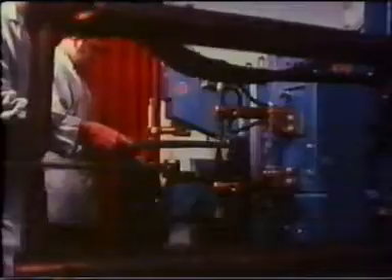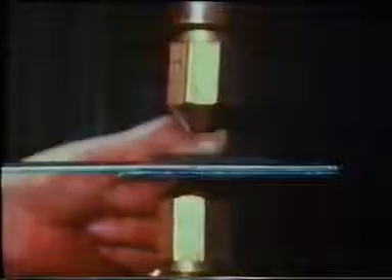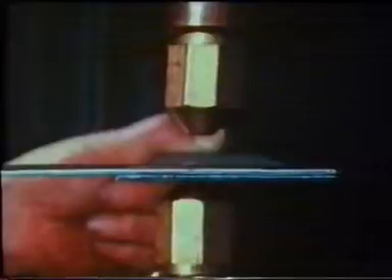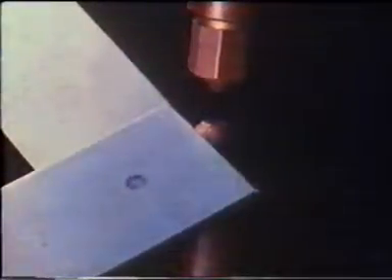The most common use of resistance welding is for spot welds. The spot welding machine is designed to carry a high current, low voltage supply to a pair of copper bar electrodes. The tips are tapered or domed to increase the resistance and concentrate the heat into a small area. The face diameter of the electrode tip must be correct for the job in hand. Progressive wear increases the face diameter, causing loss of current concentration and effective weld heat. Now, watch this. Simple, isn't it? Let's take a closer look at what happens.